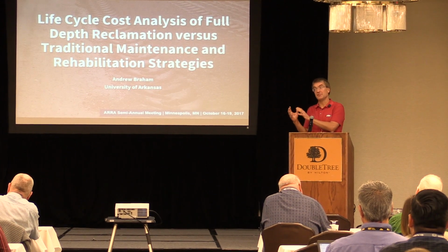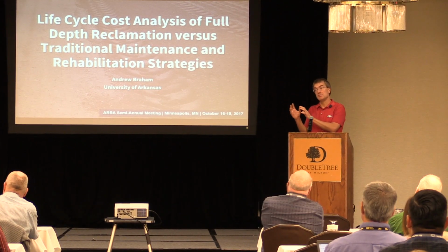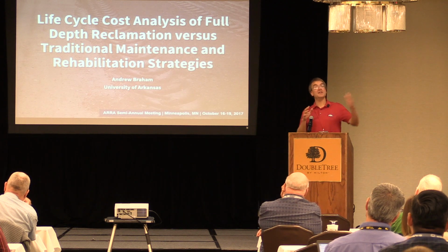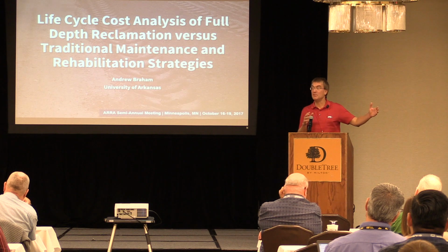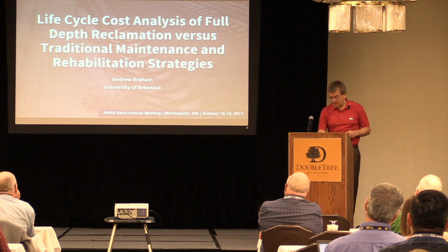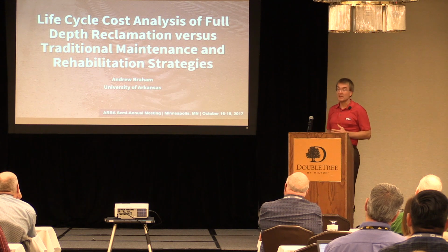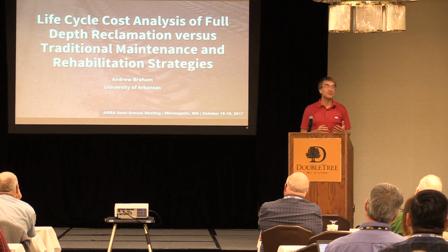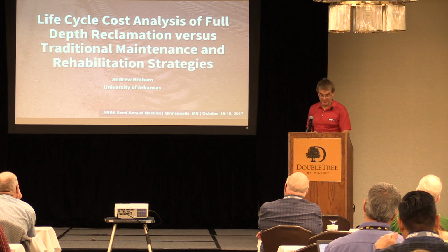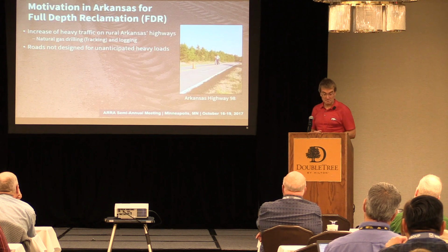And what I'm going to do is talk about not only initial prices and not only initial materials or agency prices, but also putting agency and user costs together and then seeing how over a timeline, over a 50-year timeline, we can look at costs. And what we did is we specifically focused on full depth reclamation as an alternative to some of the traditional maintenance and rehabilitation activities in the state of Arkansas.